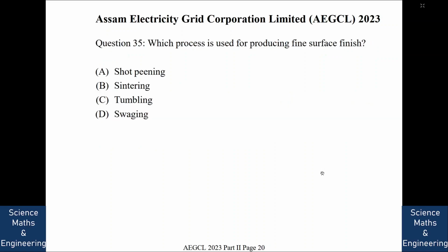If our abrasive grains are worn out, the cutting points of the grinding wheel will no longer be there, and so it will become dull. So it will provide only a smooth rubbing action, which is known as glazing. Okay, so go to the next question.